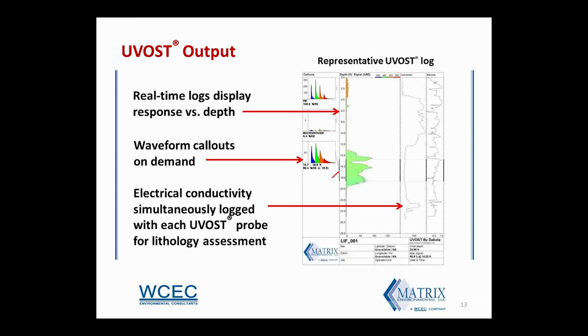Now notice also there's a correlation of EC. This is the electrical conductivity here, and you can see as it's going along with depth, there's some pretty fine-grained material here. It gets into more of a coarse-grained material, and here we have a nice correlation with where the LNAPL is hanging out, and there's a little nub right here that may not have had as obvious of a connection to the lithology, but it is useful to have this electrical conductivity data.